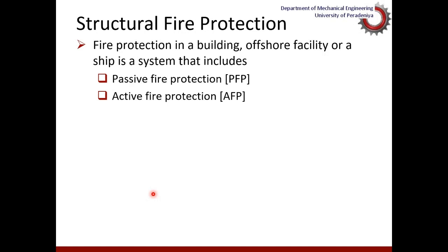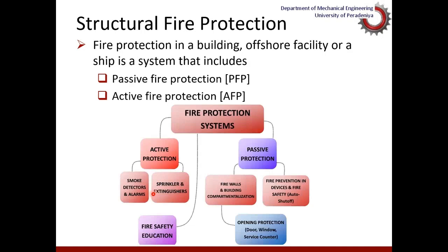That will at least confine the fire to a certain room or something like that, and it keeps the fire from growing beyond that fire door. So the fire doors are also designed to sustain at least for 30 minutes for the same reason I said. And active fire protection systems can be automatic systems or manual systems, where you do some activities to suppress fire.